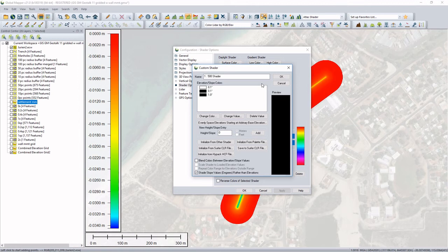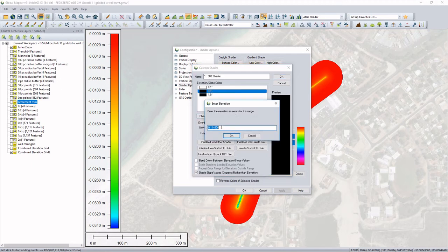Anything more than that, we start to see visual effects of those settlements as the building stretches. So I've created a shader which only shows the portion which is greater than 1 in 500, which is the equivalent of 0.11460 degrees, rather precise.